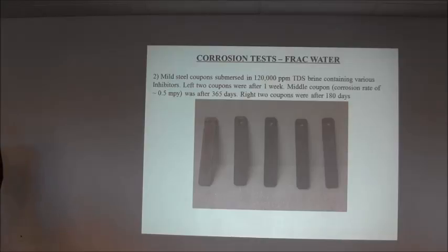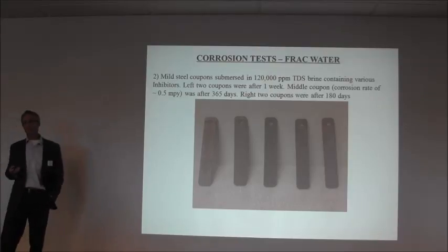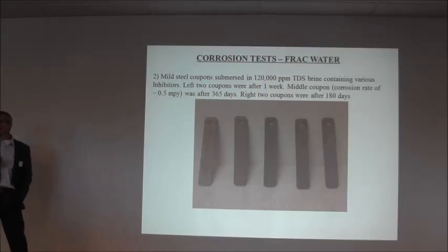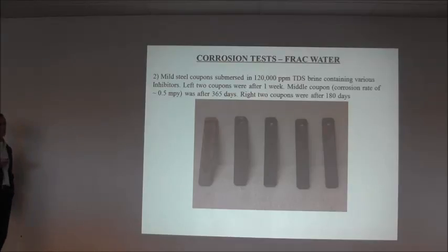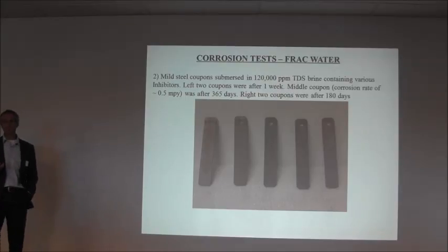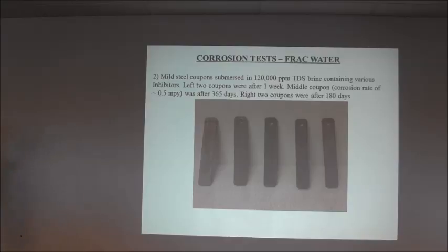Again, just additional corrosion tests. When you're looking at corrosion inhibition chemistry for high salinity brine and oxygen, you look at the literature from just about any company's products where they talk about the corrosion inhibitor that's effective in the presence of oxygen and high salinity brine, it will inevitably have some type of phosphonate chemistry in there. There's several different types of phosphonates, and each one of them has varying degrees of corrosion inhibition capabilities under certain conditions.